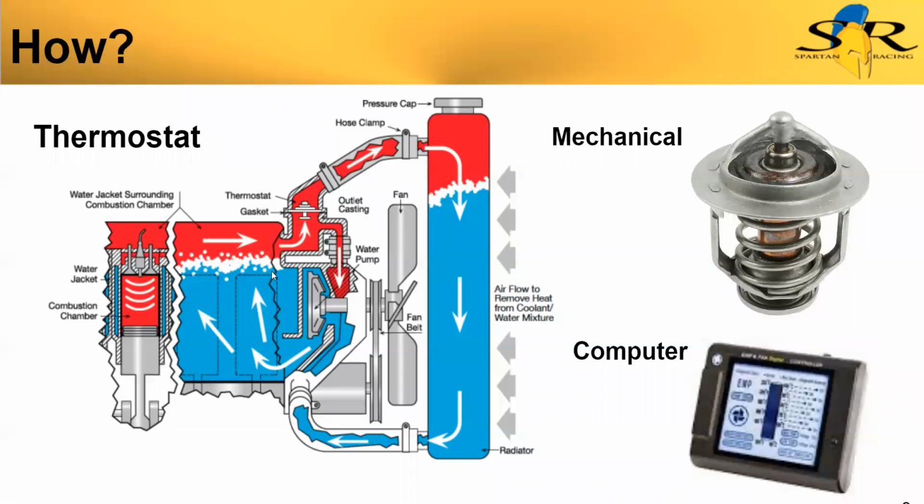It's important that circulation continues to happen, because if water sits in one place in the engine, specifically around the valves and the combustion chamber, it's going to get too hot and it's going to boil over. And computer controlled is ideal. In a lot of situations, you can more closely control the water flow, and that is used in conjunction with an electric water pump.